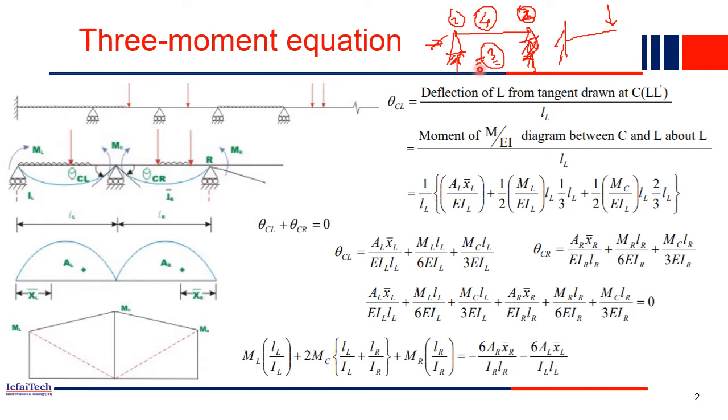Similarly, you can have a continuous beam. If you visit a university, you will find that basically all the beams are continuous beams. Here you have one column which is fixed, then another column which is maybe a roller, another column, and a single beam is continuous over all the spans. So these beams we call continuous beams. This is an indeterminate structure. Continuous beams are normally indeterminate in nature.